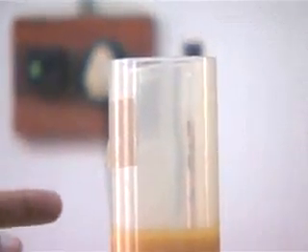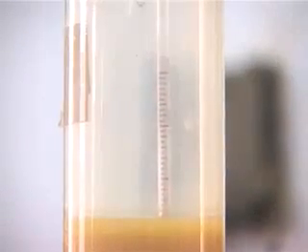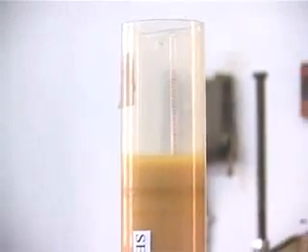So we have to be very careful with this, and you can see the reading at the meniscus for this hydrometer position is about 1009, for the level of the slurry that intersects the hydrometer stem.